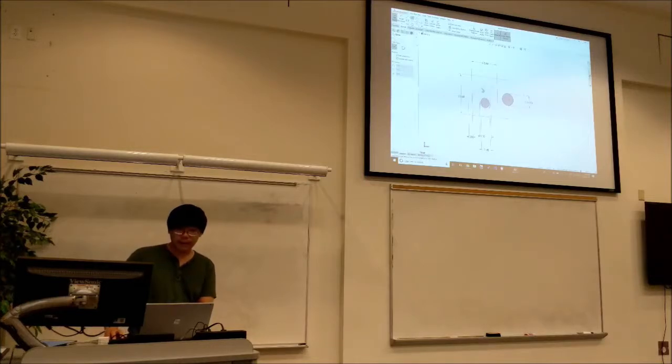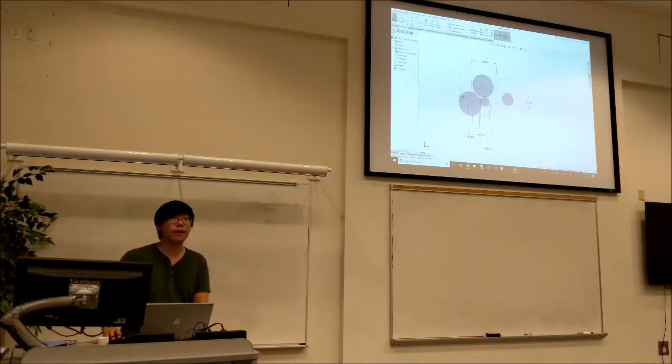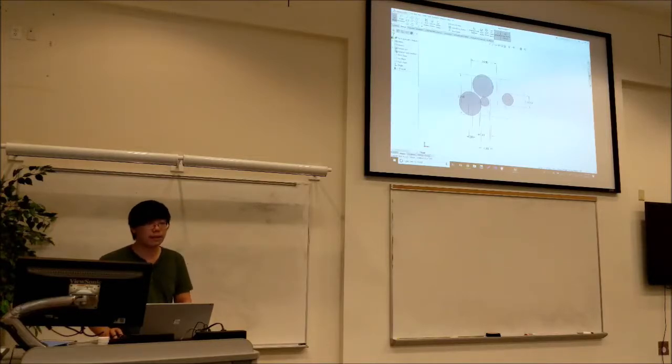Now we can actually, I guess, represent what the 775 Pro is going to look like in the gearbox by drawing two larger circles. And that's just helpful because you don't want to design your gearbox and realize like your motors are intersecting each other or something. So if you draw it in the sketch initially, you'll be able to plan everything out, and then hopefully if everything works out, you'll be able to just do it once and not like 5 times.